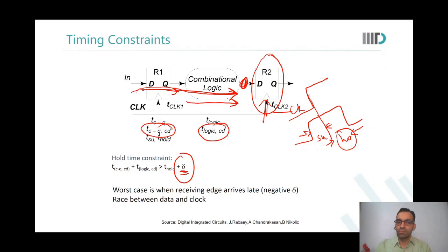So, sir, when the same clock edge arrives at both flip-flops, the first will start processing, and for the next flip-flop I want the latching to happen, not this input to be transmitted to that. Yes. But why, in the previous slides, when we were considering contamination and propagation, you were saying that for the contamination delay we are not sure that the data, the Q, will be stable or not.